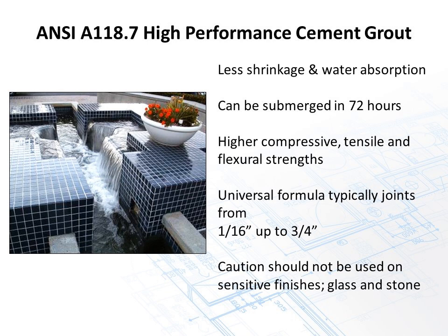I always recommend, if the grout has an aggregate in it, regardless of how fine that is, that you test it against some of those sensitive finishes like glass and stone. Make sure it's not scratching it.